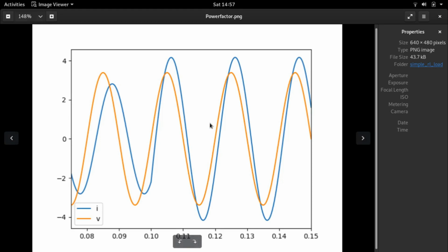This is how we have simulated a kind of load change, right? So we have now progressed from having a fixed inductance and a fixed resistance symbolizing a particular load to a variable resistance and a variable inductance, right? So now we can simulate changes in the load. So things like this we can simulate. For example, if you're simulating a simple load connected to a particular AC generator, you can use this and you can increase or decrease the values of resistance and inductance and therefore see the effect on the generator, right?